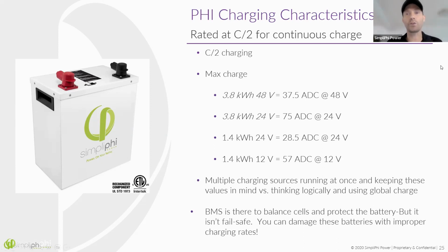So it's got a C/2 rate. C/2 means the capacity of the battery can be, you can either drain the battery or fully charge the battery in 2 hours. That's what the C/2 rate means. So if your battery is at a 50% state of charge, and you want to know how long it would take to charge it up fastest, you would be able to top that battery off if it's at 50%, would be 1 hour, right?